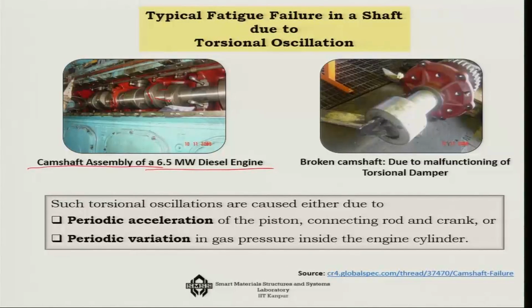So, that periodic excitation force actually creates a periodic acceleration of the piston, the connecting rod and the crank. So, this crank is subjected to a periodic excitation force. Now, if that happens, then this kind of system will at the end develop a fatigue, and as a result you will see this kind of failure that has happened to the system.